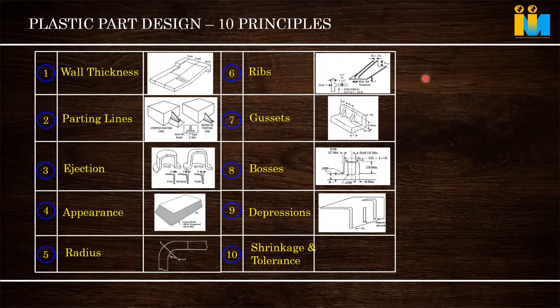It's not a hard and fast rule. You ask for this material, but because length changes, it changes. Thickness changes, it changes. Melt temperature, hot runner, it changes. Cold runner, it changes. So there is a thumb rule to understand roughly, but you cannot say all parts will behave the same way. To give that indication, we have MFI. MFI is already there in the data sheet. My material polycarbonate has 10 MFI. If I feel I have to reduce thickness a little bit, 0.1, 0.2, I go for an MFI of 18, or go for a 20 or 22 MFI. This is how it has to be done.